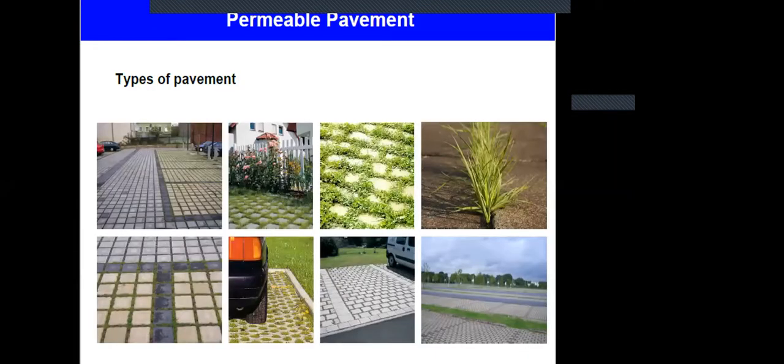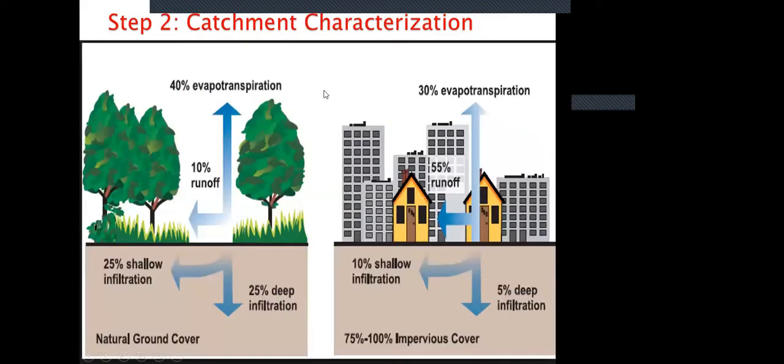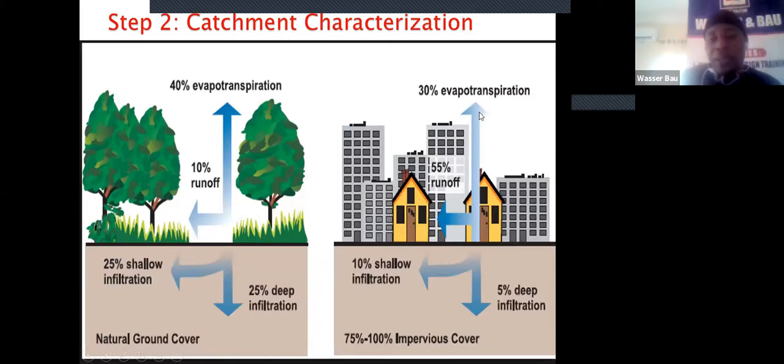In two of the diagrams, you say one has a coefficient of runoff of 0.55 and the other 0.1. I don't know what is the basis behind it. Good. The basis is that the one on your right has a higher degree of paving, a high density area. So of all the rainstorm that comes here, only 10% will go into shallow infiltration, only 15% will go into the groundwater, and 30% will go back into the atmosphere as evapotranspiration. So you now have 55% volume to deal with.